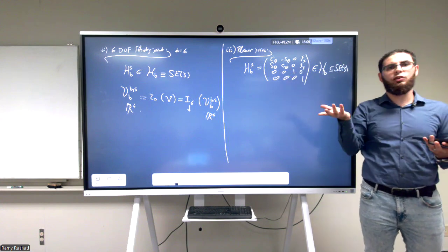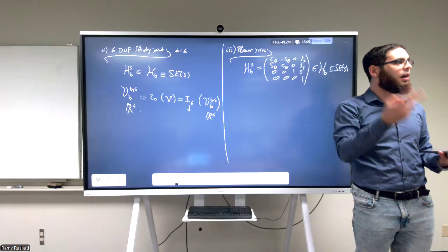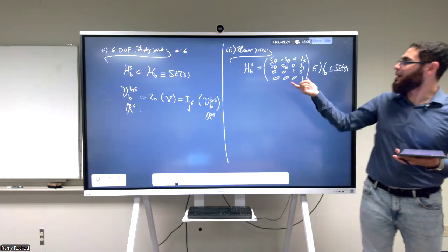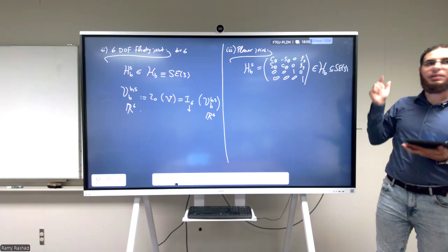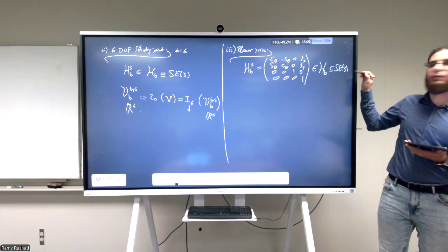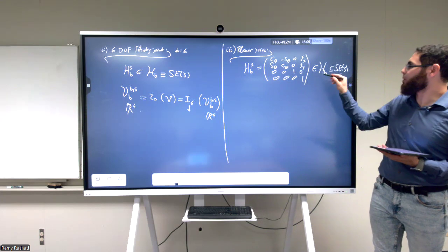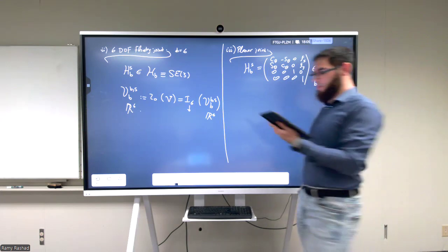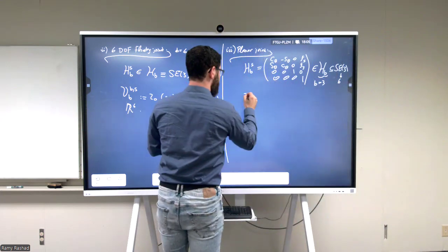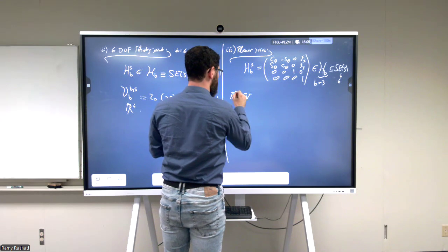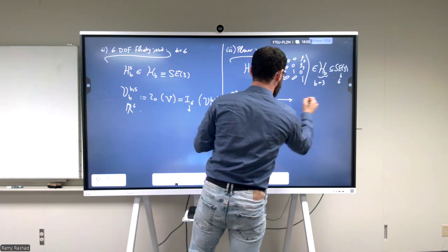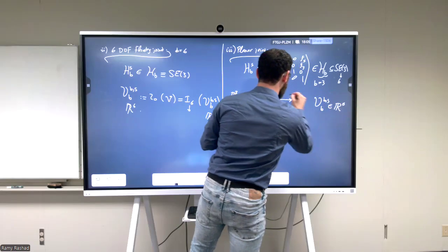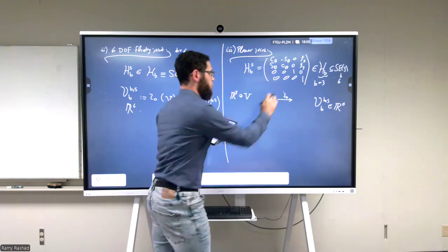And this is exactly what you always do in 2D when you have a mobile robot on the ground. You say that you have 3 variables that describe the configuration, X and Y and angle theta. You put them in an H matrix like this, and you get something that lives in SE3. But it's not everything in there. SE3 has 6 dimensions. What about the dimensions here? B is equal to 3, exactly. So now I want something that will map V that lives in R3 to the twist that lives in R6. And this map, we're going to call iota, without a dot.